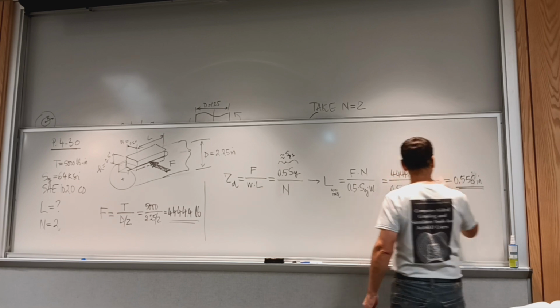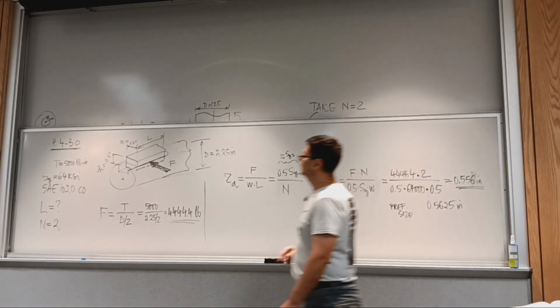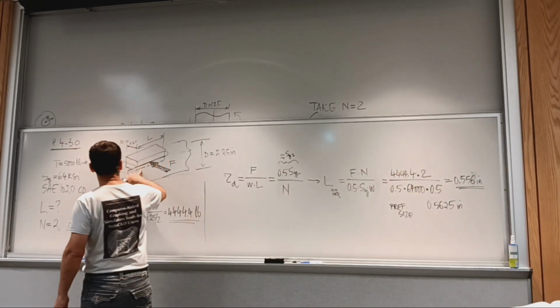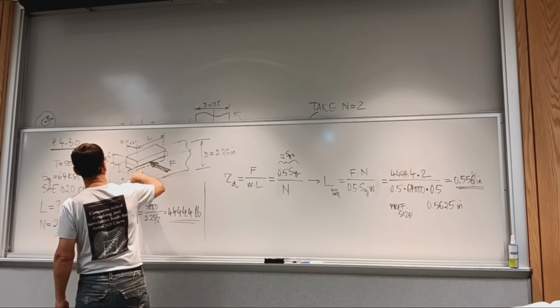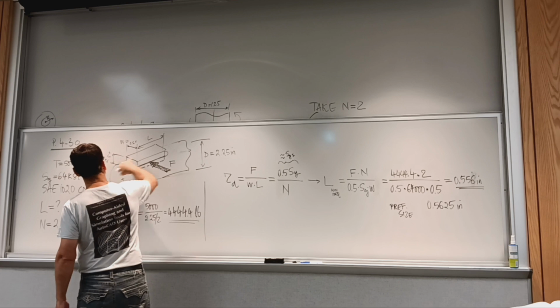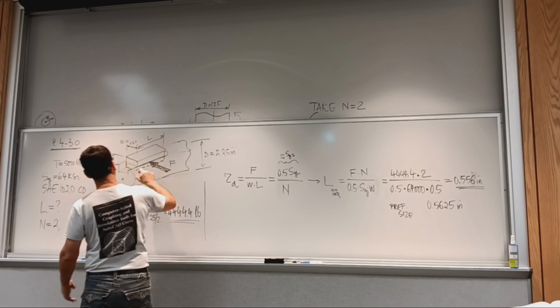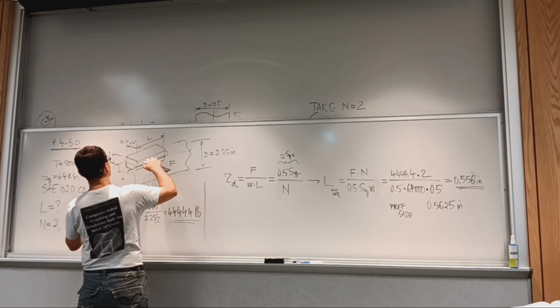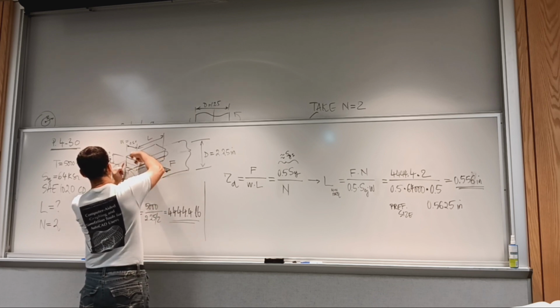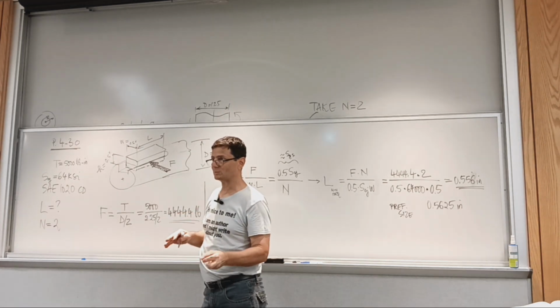So now I have a length, and we can calculate the bearing stress. Okay. So where is bearing going to occur? It is going to occur between this face of the key set and this side, or depending on how the torque is delivered, contact may be made here and here, or the other way, depending on the direction between hub and key and shaft and key. Do you understand what I'm saying here?